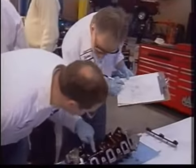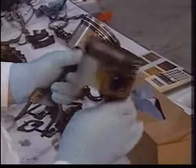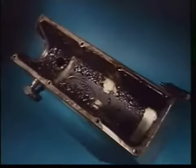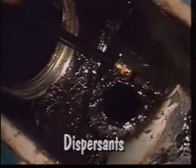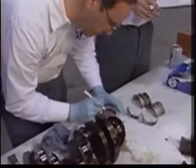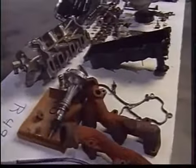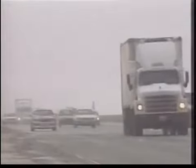Detergents protect parts against carbon and varnish buildup, which is vital for parts with close clearance, such as piston rings and skirts, valve lifters, and oil pump relief valves. Dispersants minimize the tendency of contaminants to agglomerate into large lumps, which settle out as sludge or varnish. Although both dispersants and detergents act as cleanliness agents, they differ chemically. Dispersants are non-metallic materials and are more effective than metallic detergents in controlling engine deposits under intermittent or low-temperature operations.